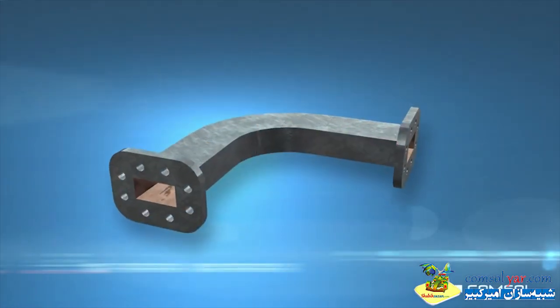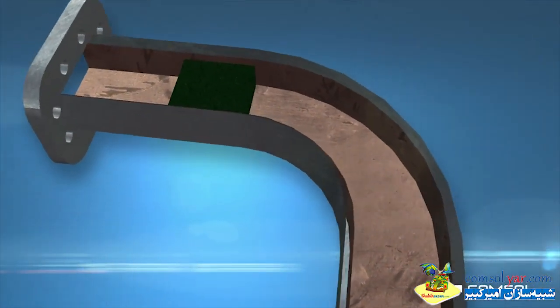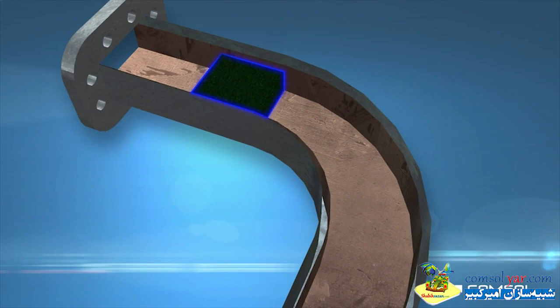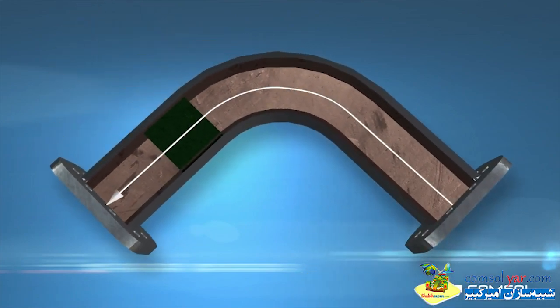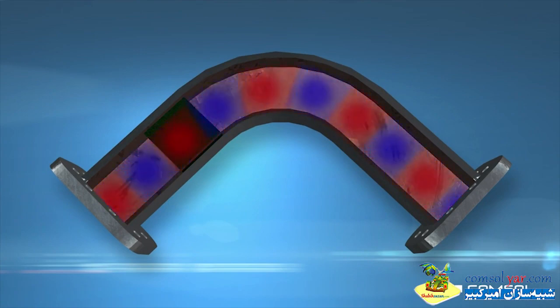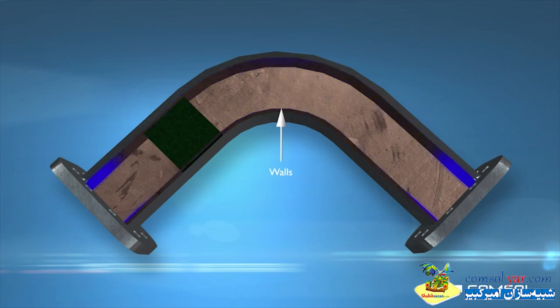In this model, we will simulate RF heating of a waveguide bend containing a dielectric block. A guided wave enters the assembly on one side and propagates throughout the waveguide structure, interacting with the walls and dielectric block. The waveguide will experience electromagnetic losses in the block and waveguide walls, which will induce a temperature rise in the assembly, leading to thermal expansion.